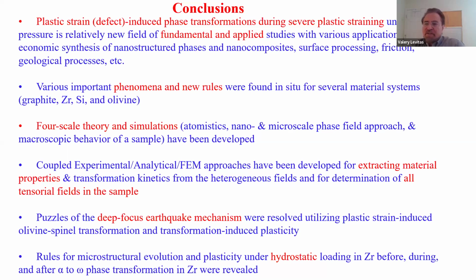So if you want to cause a phase transition, either pressure should be very high, or if pressure is low, then plastic strain should be significant, for example, in a shear band. If it's pressure-induced amorphization, it's a completely different story. If it's relatively low pressure and large plastic shear in a shear band, then I believe this is the same. And there are a lot of recent reviews, in particular from Lawrence Livermore and Mark Myers.